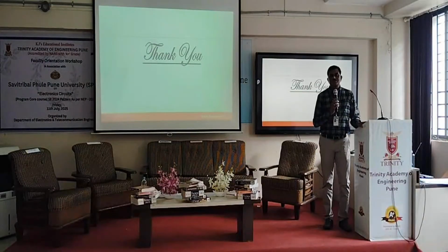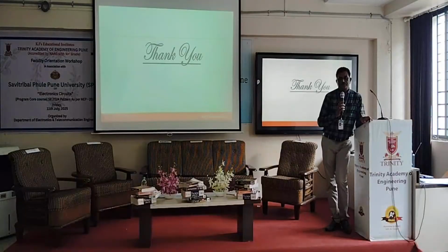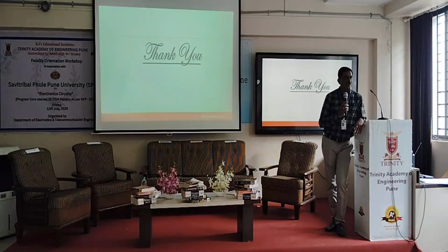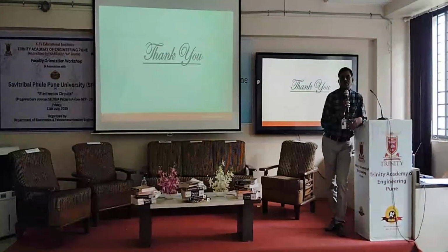Only symmetrical we have considered, and from the practical point of view, given the values of the VUT and VLT, calculate the value of R1 and R2, assume any one and calculate the other, and simulate as well as implement using the hardware also. It's a simple thing.